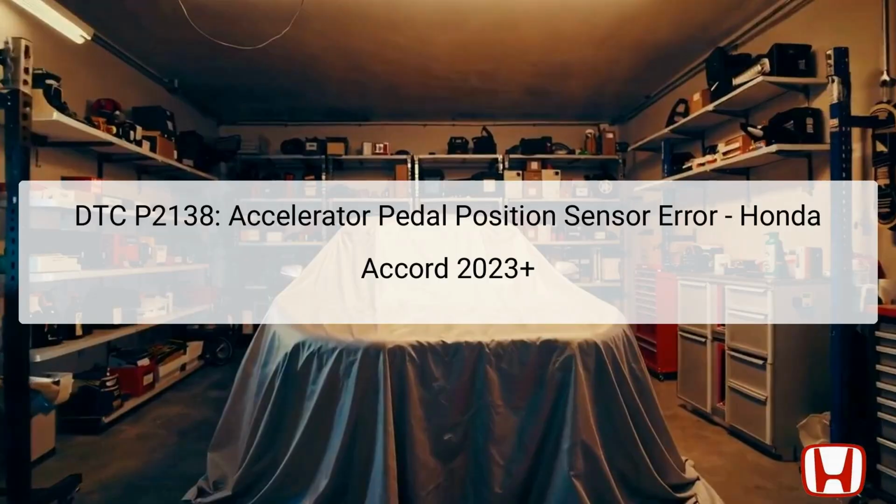The Diagnostic Trouble Code DTC P2138 indicates a malfunction with the accelerator pedal position, APP, sensor A and/or B. This error arises when the voltage correlation between these two sensors does not match up according to the Powertrain Control Module, PCM.